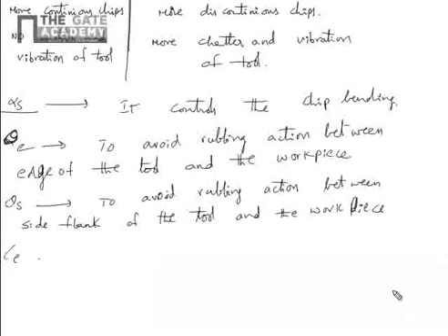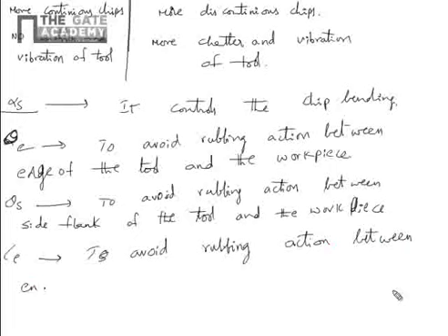End cutting edge angle, same as the end relief angle, but here also to avoid the rubbing action between the edge of the end flank and the workpiece.